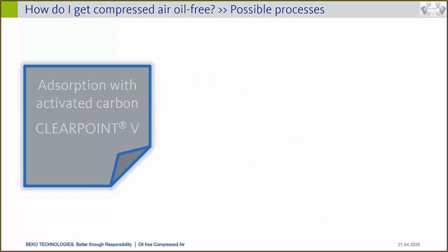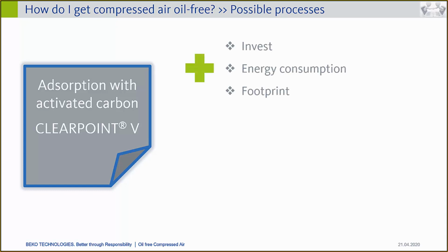So the next point is the adsorption with activated carbon, and in our opinion, that's the clear point versus. On the positive side, we have the invest. Of course, it's a very cheap setup. It's a very simple construction, so that's the reason why it's quite low in invest. The energy consumption is, of course, a positive point because that equipment does not require any power supply. And also the footprint is a positive argument. It has a small size and a low weight compared to other treatment systems.